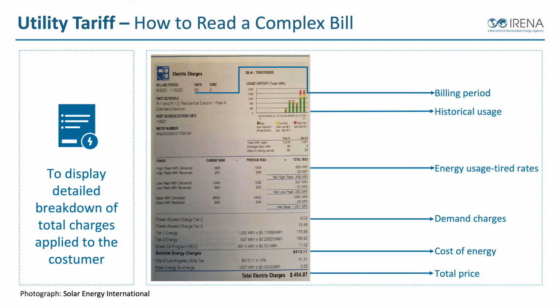We have what we call demand charges. Some utilities put demand charges on residential buildings. A lot of them only do demand charges on commercial and industrial applications, so you need to look at that as well. Demand charge means: what is the peak kilowatt consumption into that building during that billing period or that month or 2? Because the utility has to supply you with all the energy that you can take, they're going to charge you for the highest demand, or the highest watts or kilowatts draw, that you ever pull from that utility.